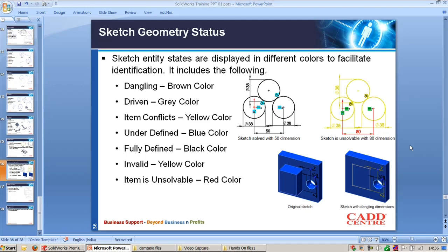If you know only the creation of sketch and editing of sketch and applying geometry relations and doing dimensioning, without understanding the different colors, that is the geometry status, you will not be able to define it fully to be parametrically controlled. And that's all about the sketcher environment of SolidWorks. I hope this session will definitely give you a better view on sketching 2D entities.